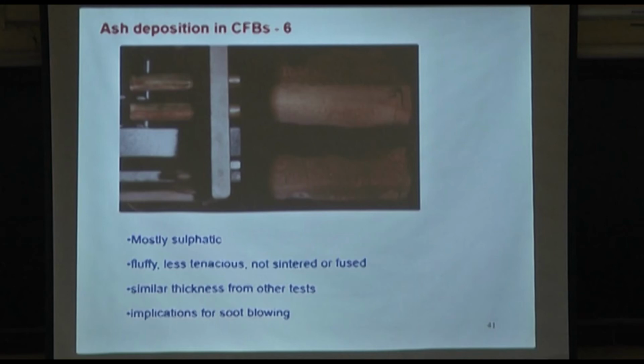Okay, so it's not just aluminum oxide or silica. If they were the main ones, there would not be a problem. Same thing, the sodium, calcium, magnesium, iron, they're combined. So in some cases, in this case, for example, it was sodium sulfate, because we had so much inorganically bonded sodium sulfur there. Such a high amount of sodium was in this coal, very salty coal. That was creating the problem.